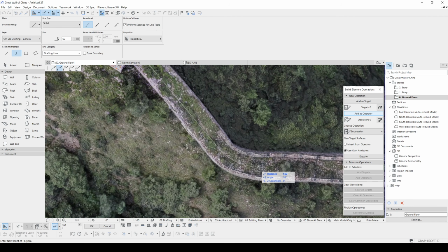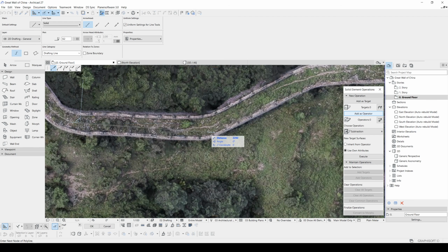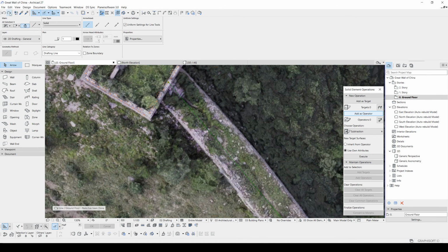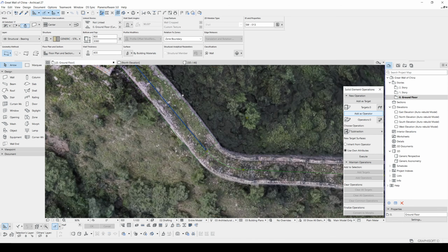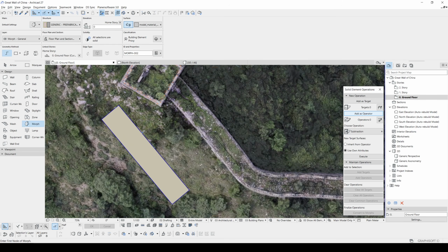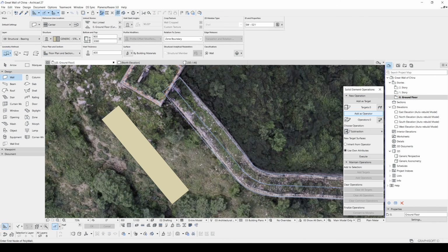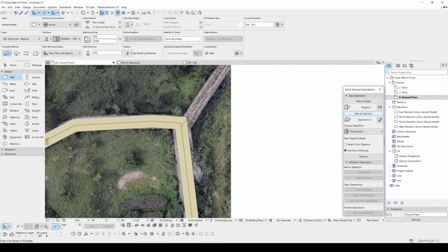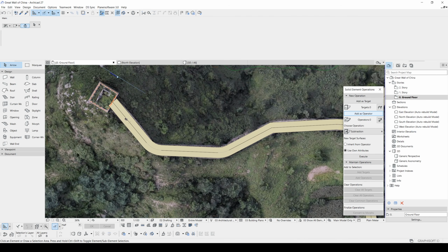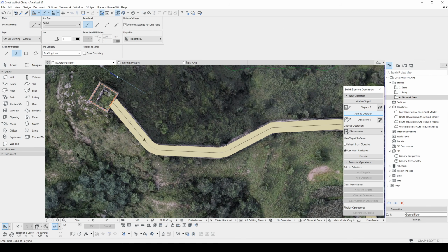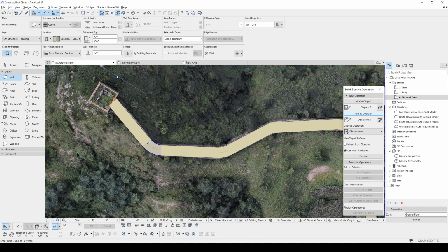As for the corners, you can use the curve, and then you can continue with straight lines. If it's hard to model, you can just use simple corners. Anyway, once this is done, we are just going to overwrite the lines with the wall tool, with the correct sizes and thickness. Hit the spacebar to use the magic wand tool, and there we go. We created our borders. But this is temporary. We are going to delete this wall and select all of the remaining wall parts, and also we can delete lines.